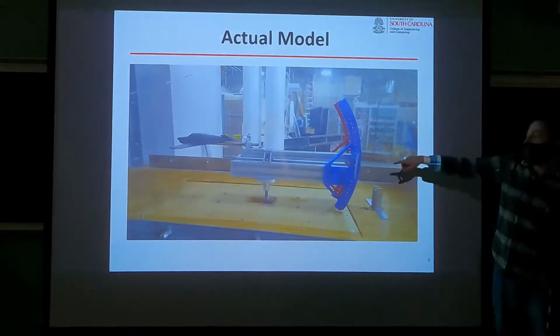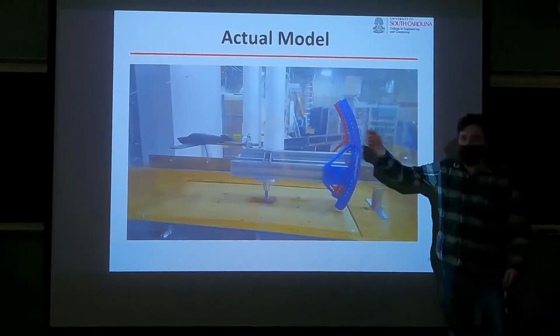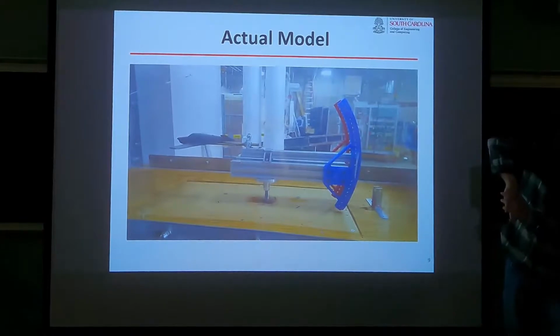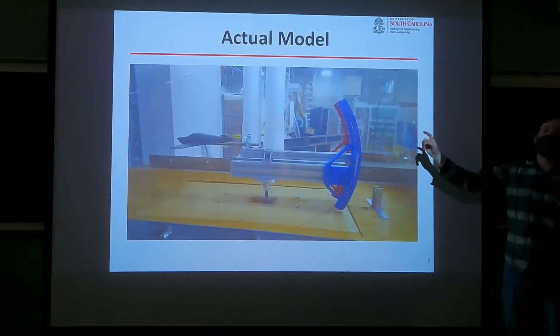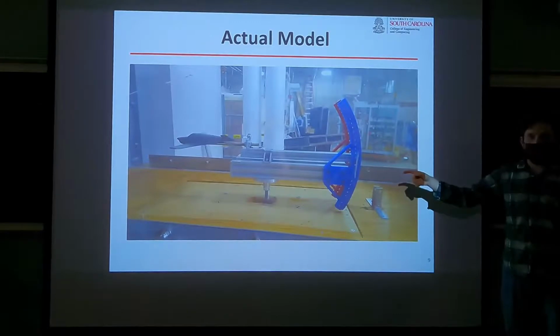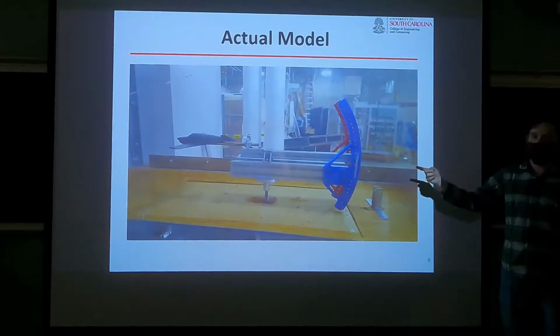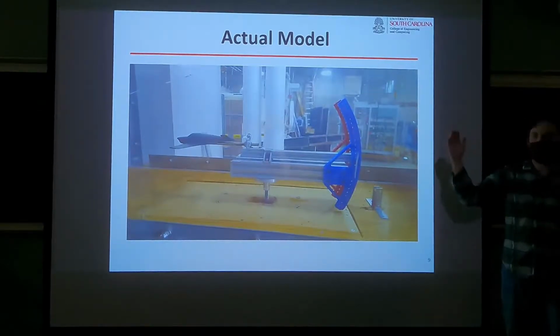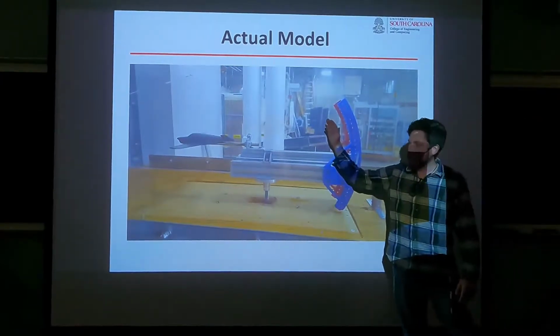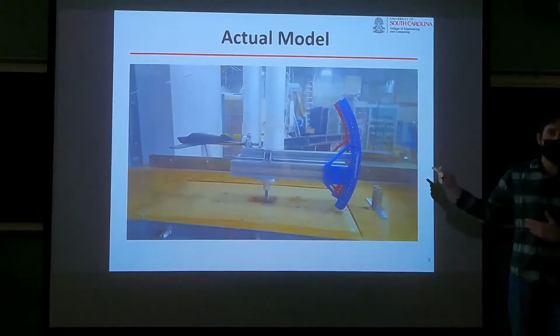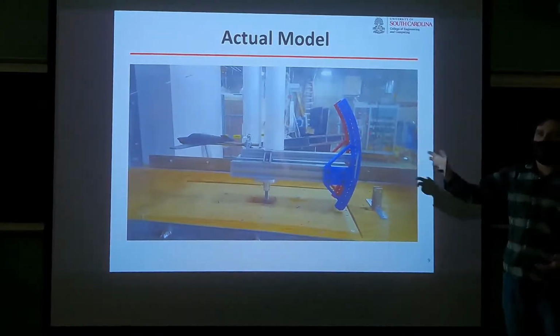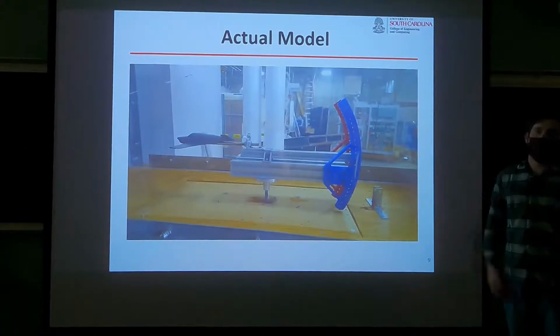So essentially we have another small thing that's also changing the angle of attack, which means the drag for the mount will also change with the angle of attack. That's why we had to do calculations for the angle of attack for just the mount itself. We put it up 20 degrees and calculated the drag, then you stick the model over there and take the difference of those two.